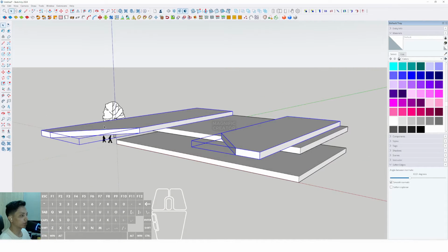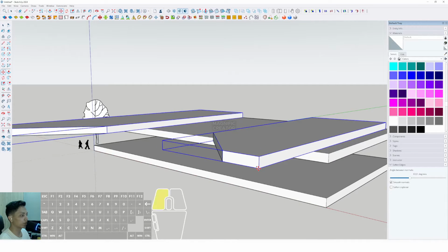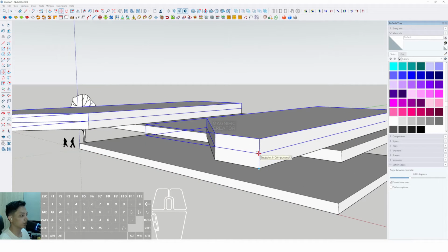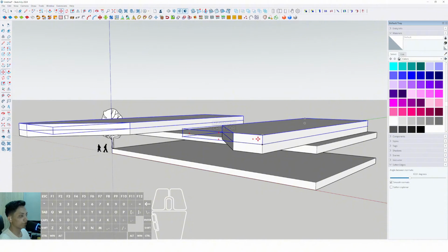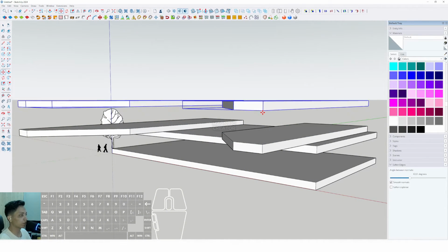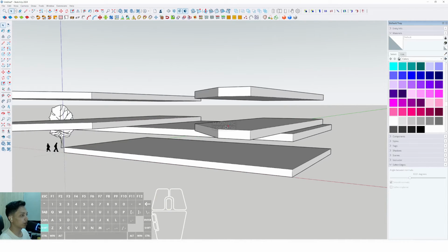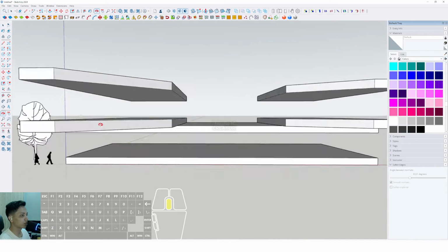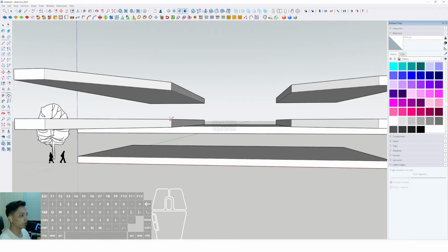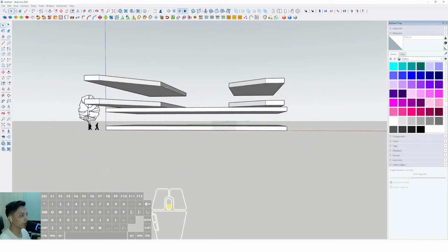And then we can click both of these basic plane meshings, and select the move tool, press Ctrl, and click from this position until above the slab. Then we have to move it up around 3.6 meter approximately. The 3.6 meter is about the floor to ceiling dimension, or the floor to ceiling distance. And I will show you the floor to ceiling distance approximately. This one is around 3.6 meter. Okay, so you can see on the screen, and I will erase it, then continue to the next step.